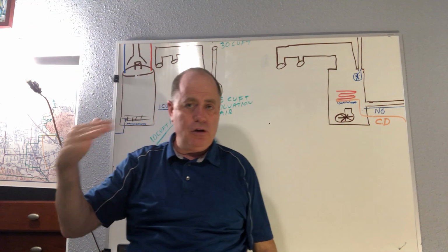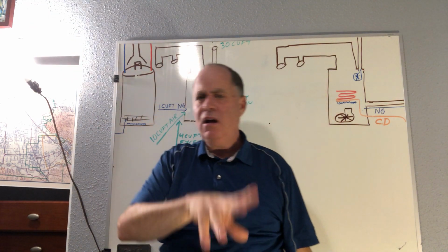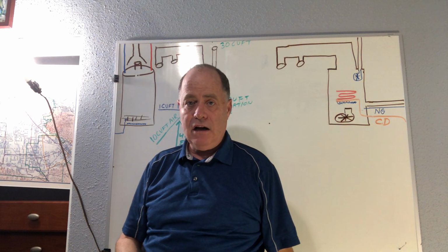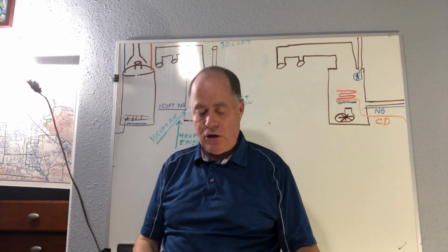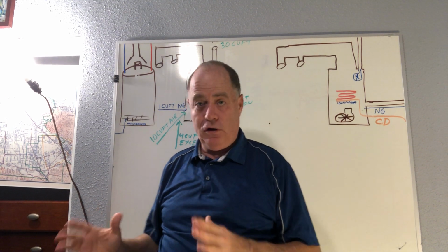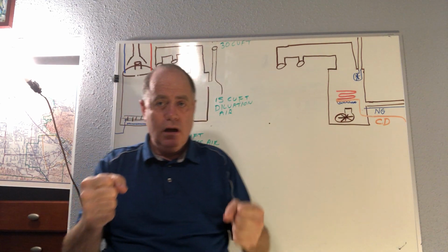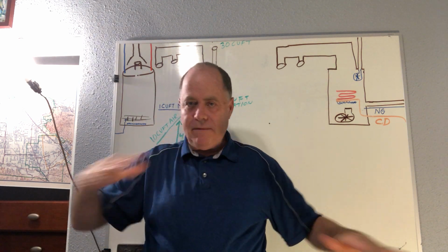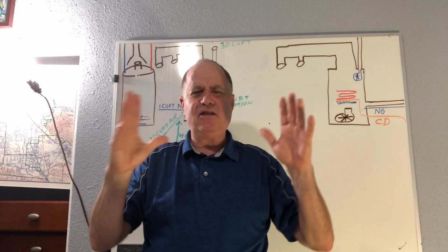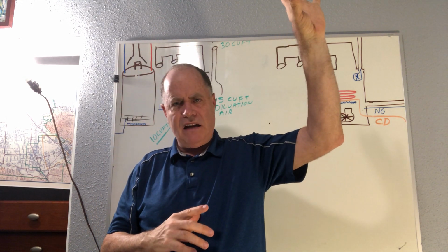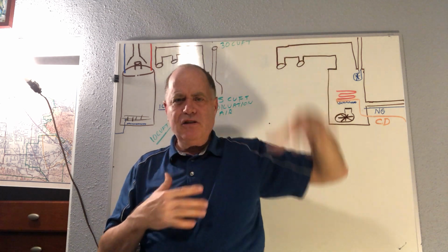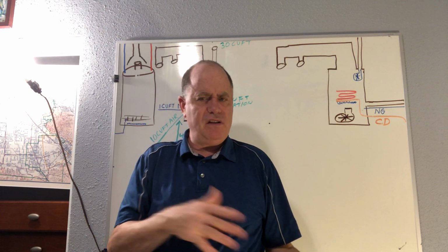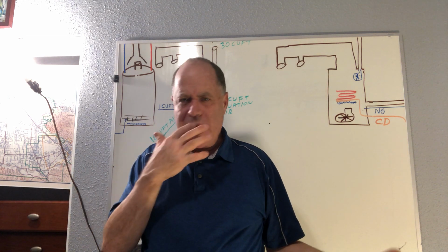So we're always trying to have a sufficient supply of air for combustion, but also for people and technicians working. You'll also see, for a furnace that's in a closet, when you open that door, it's usually an upflow type furnace where the air comes in the bottom. You'll see a vent going to the attic, and then you'll see a duct that looks like it's just stuck near the bottom of the furnace that doesn't have anything on it. And you're like, what the heck is that?